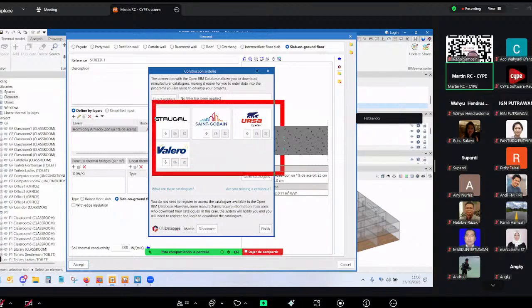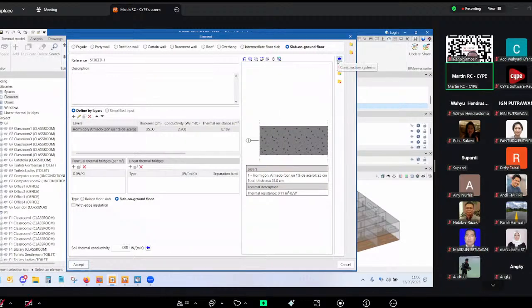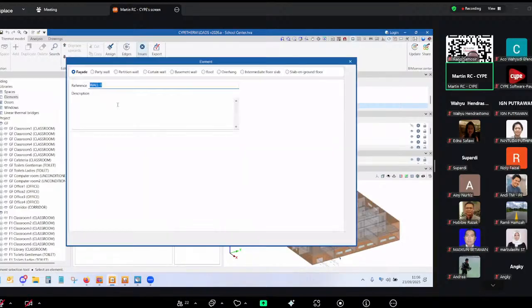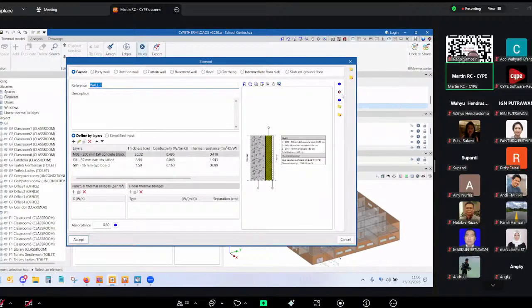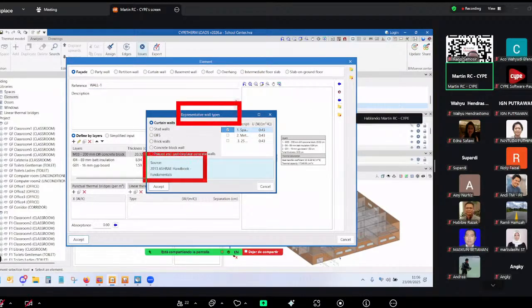And we have actual prefab solutions, like a specific, let's say, attic facade: one wall that's bricks plus air chamber plus insulation from this brand plus stucco. For example, we can just load all of them from there. So we can be really fast defining the slab on grounds, the walls. In this case, this was defined that way, just defined representative wall types according to ASHRAE.